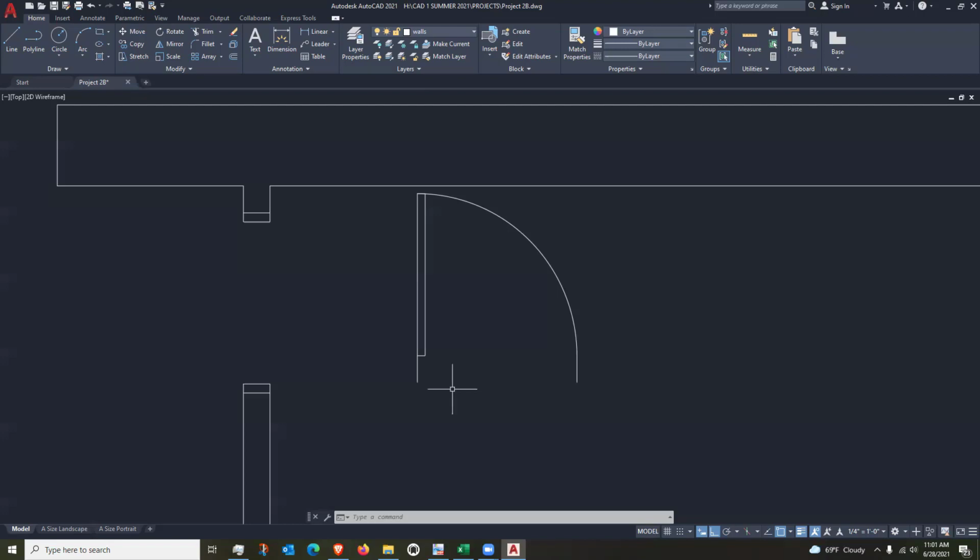The most common door jamb is 5 inches, and you'll locate that door jamb so that it straddles the gap between the back face of the brick and the front face of the concrete block.